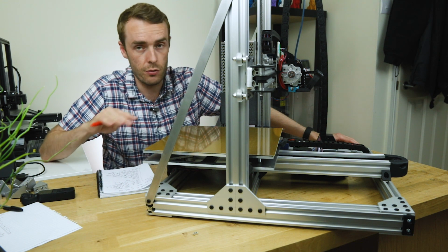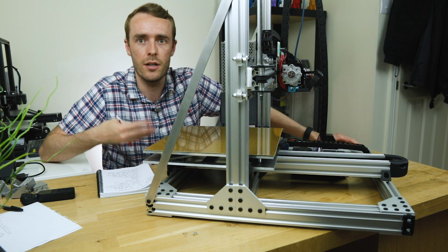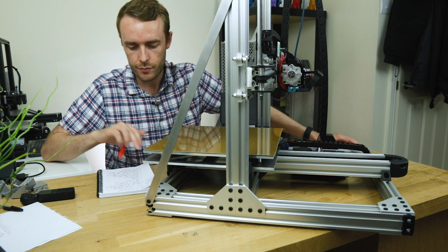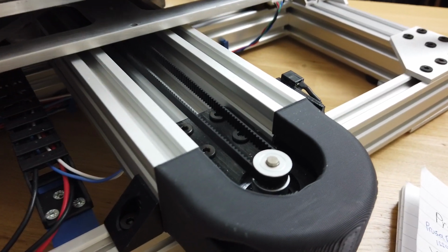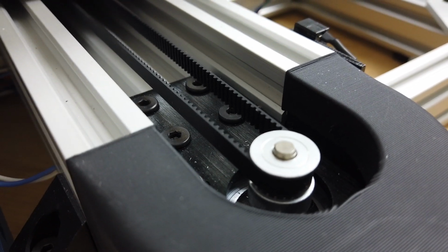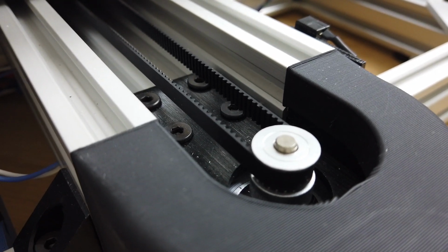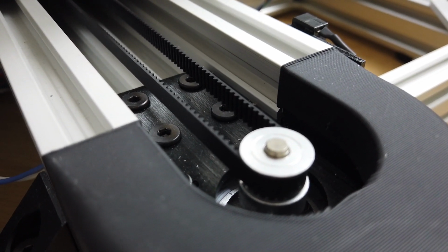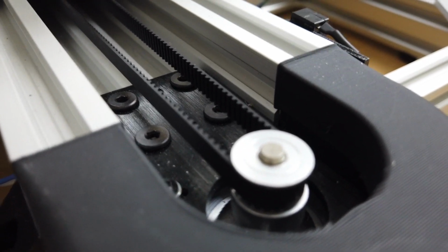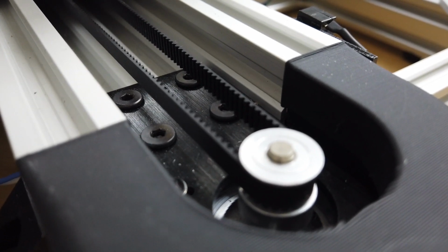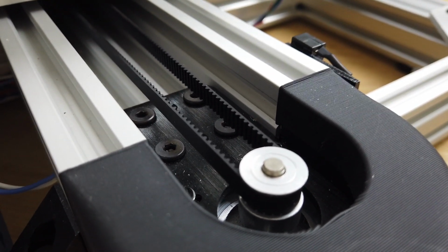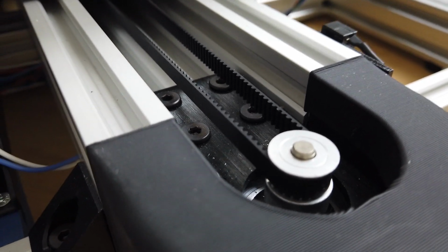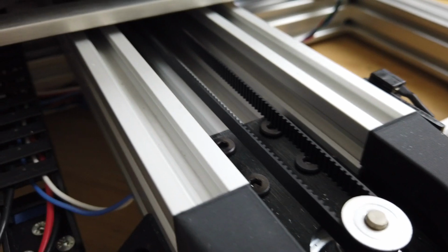Should I be trying to reduce the weight in order to increase the acceleration and improve the print speeds? Yes. So that's why we've covered that one. The belt that we're using in here at the moment is a really standard 3D printer belt, which is a 6mm wide 2GT or GT2, whichever way you like to call it. I think technically it's 2GT, but all the Chinese vendors sell it as GT2. Anyway, it's a 2mm pitch belt of the standard tooth profile you'll see on pretty much every 3D printer.